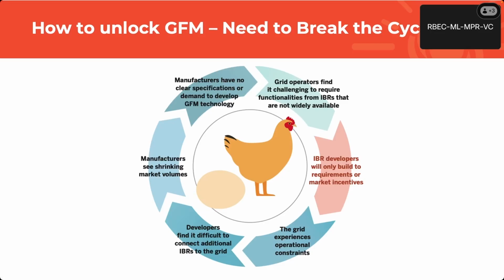So I've heard this as well. And I'm frankly a little confused by it. It might be true for some OEMs. What we've seen in the simulation models is most inverters already have some headroom. They're not operating flat out. They have a little bit of headroom. For example, if you want to provide reactive power and active power at the same time, they have current headroom. That's one thing that confuses me.